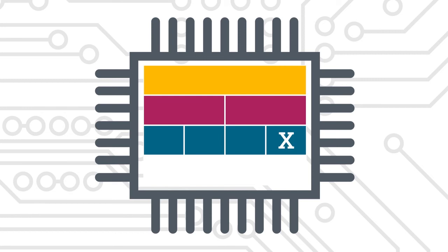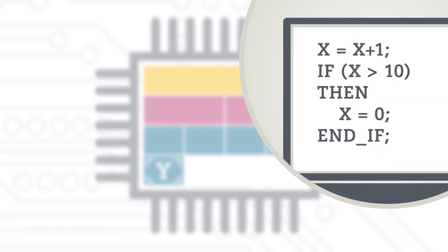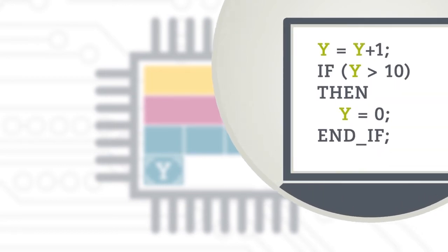During programming, tags are no longer addressed absolutely, but symbolically. The TIA Portal monitors the assignment of the symbol to its memory address. In other words, the change of an address or tag name triggers an automatic change of all use instances as well.